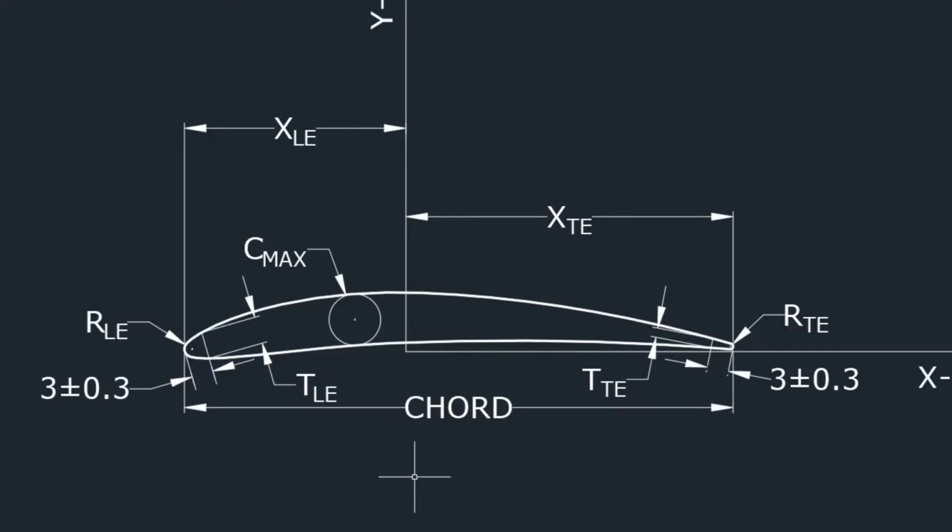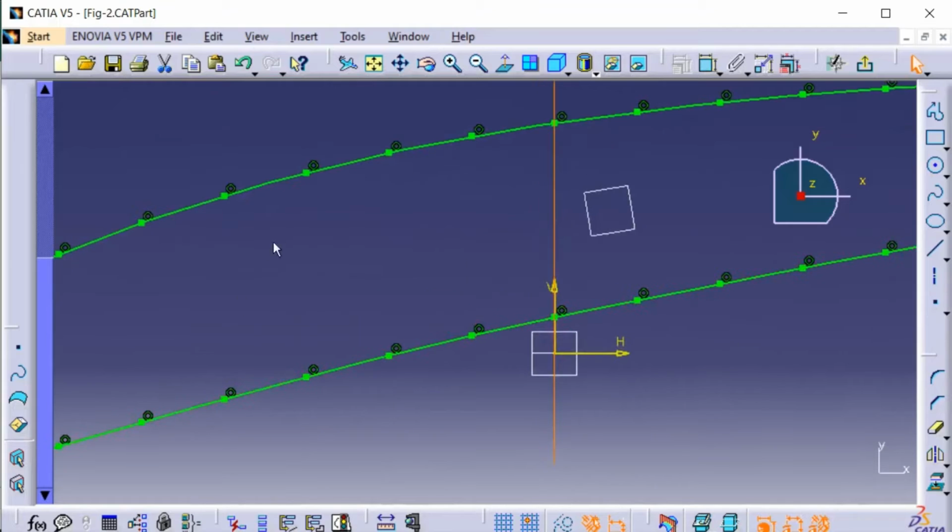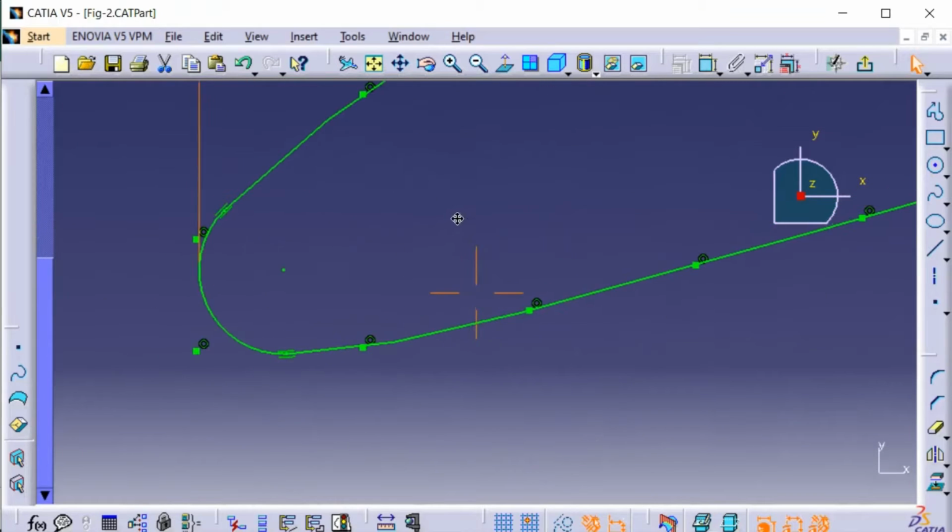So there are various techniques that you can use for actually constraining the aerofoil. These techniques have to be selected to suit our need in the industry. But one thing has to be perfect. The tangency should always be maintained in the transition or the joints. Like if you see here, you do whatever you want, but the tangency between the transitions must be maintained.